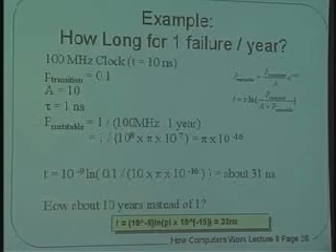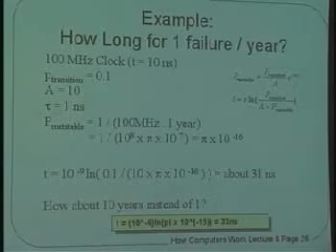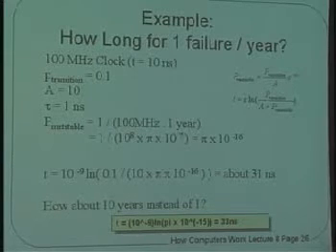And let's say that we decided that we wanted the chance that you're metastable to be the case that even though it's doing 100 million arbitrations per second, I only want one of them to go bad every year, that I'm willing for my system to freeze up once per year, because after all, it's running Windows and it freezes up once a day anyway. Right? So once a year is a good number to use.